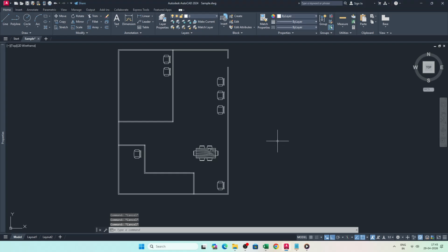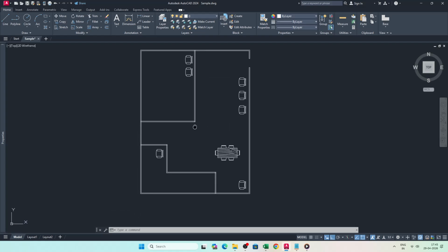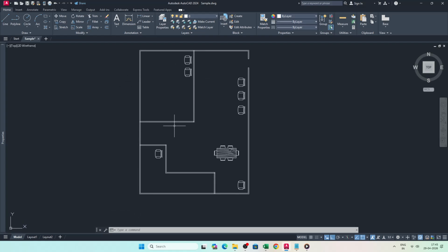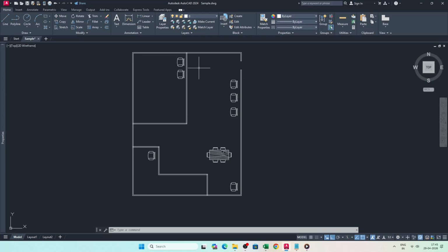In today's video, I am going to teach you about AutoCAD dimensions not showing. Why are my dimensions not showing? Dimensions not working in AutoCAD. If your dimensions seem to vanish or never appear, the most common cause is a layer visibility issue.